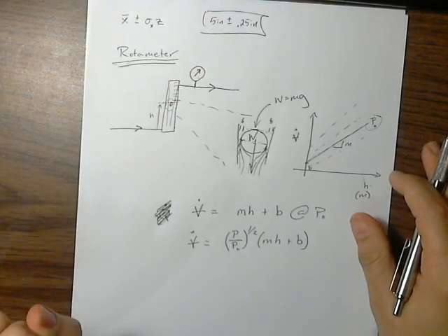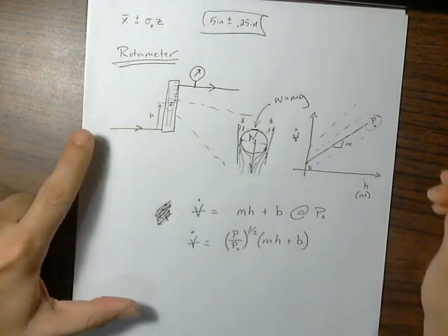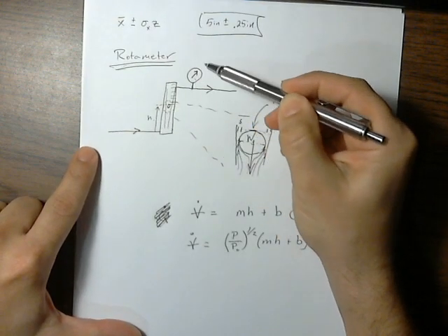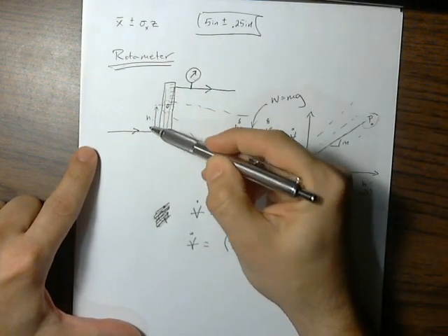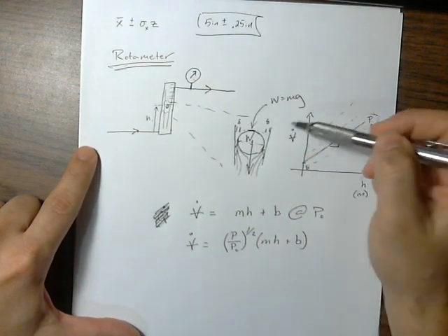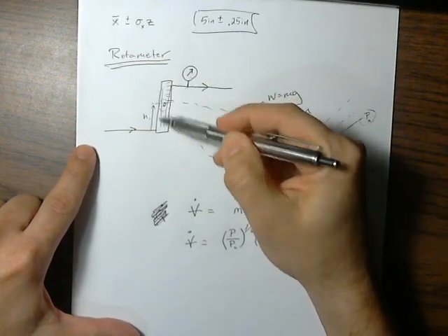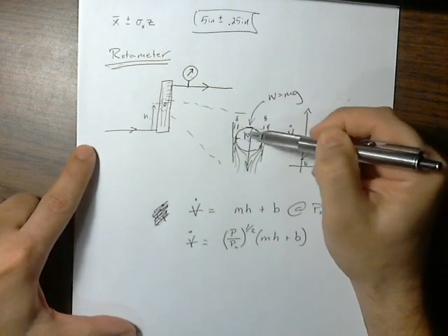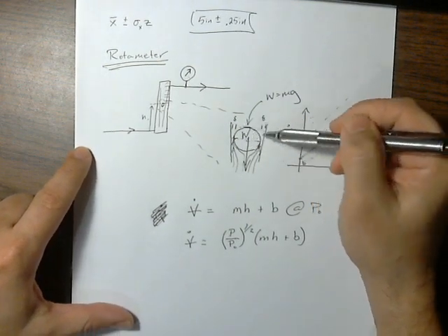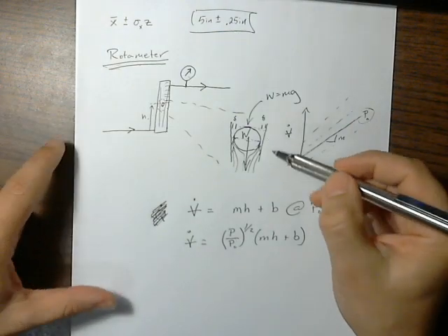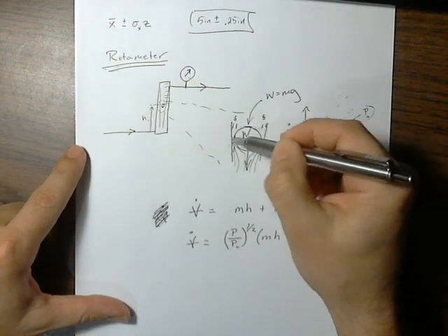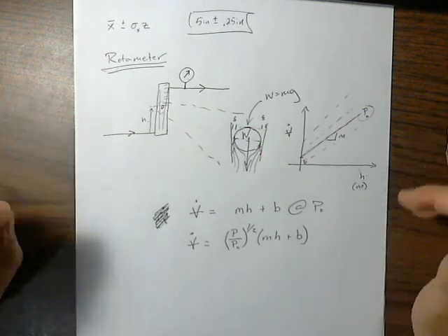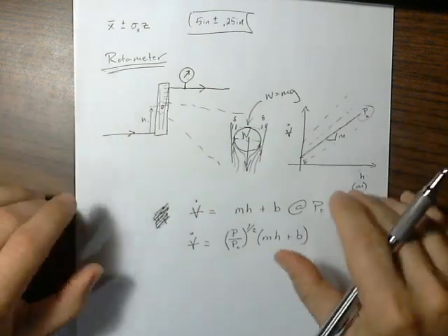Okay, so terrific. That's great. But here's the problem. We now have two direct measurements. One is a pressure measurement from a pressure gauge, and the second is a height measurement from a millimeter graduation here. And as we've already established, there is some error induced just by reading the scale here. And if your manufacturer is one of the stupid ones that thinks that you should read from the middle of the ball, well, then you're stuck with this less precise method, which is really irritating.